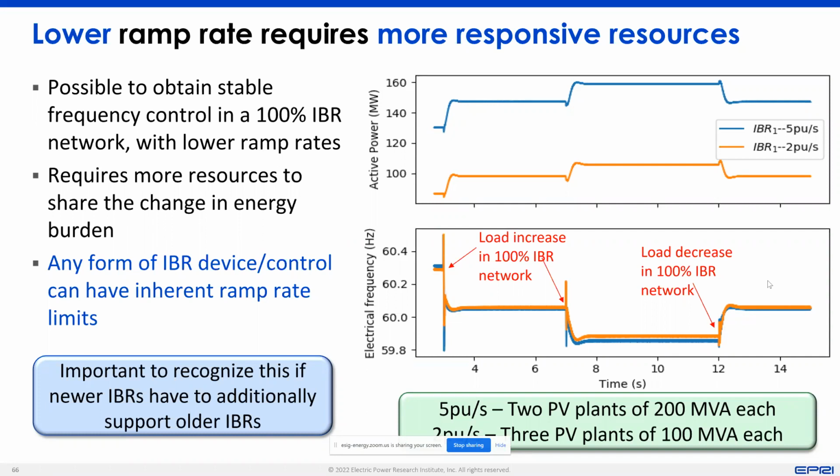So your controls must make voltage healthy before you can stuff the megawatts. Gotta be healthy, not only where they're being injected, but where they're being delivered to. And that gets lost in this conversation. So just stuff the megawatts? It's not the right answer. Voltage first, then watts. That's why the presentation had voltage first, then watts.